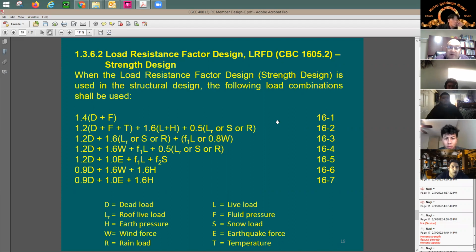So I'm not certain about the self weight of the members because it could be a little bit thicker. Also, I'm not sure about the weight of the tiles. When I do a design here, I'm going to put a value for it. I'm going to say, let's say 5 pounds per square foot. And all of a sudden, the person who's doing it decided to put porcelain tiles. It's going to be maybe 3/8 of an inch thick.